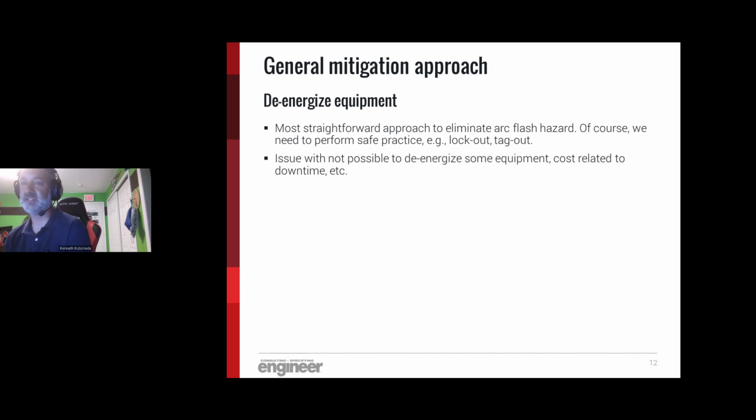To do this, operational maintenance procedures can be developed to shut down the equipment before any work is performed, things like lockout, tagout procedures. You can also add key interlocks that can prevent opening equipment while it's energized. You see this a lot on medium voltage transformers where the upstream and downstream breakers will have key interlocks. Once those two breakers upstream and downstream are open, you take the key and it allows you to gain access to that piece of equipment. So it has to be de-energized before you can actually work in it.